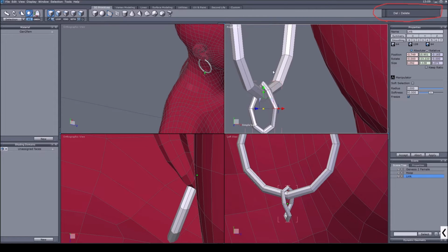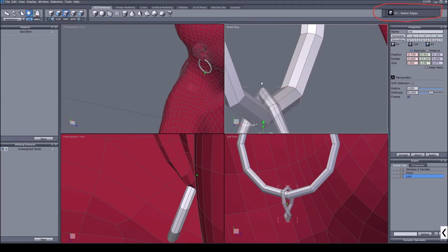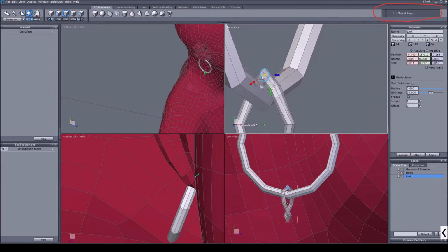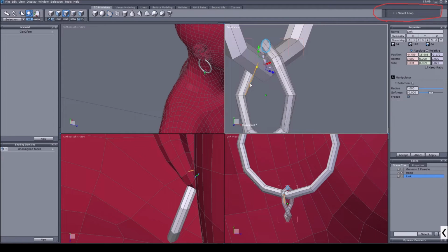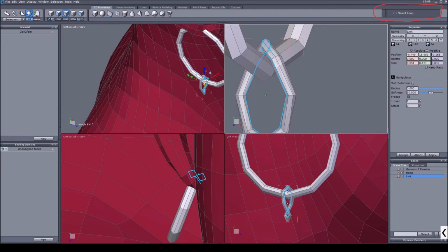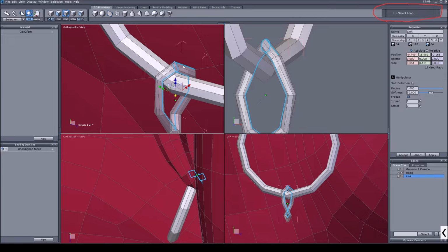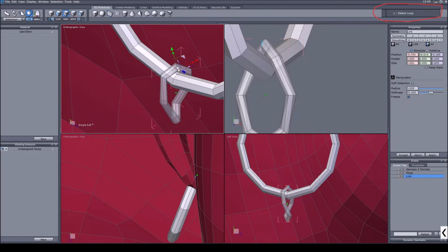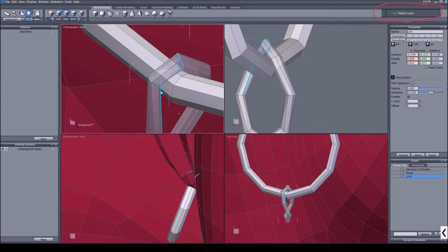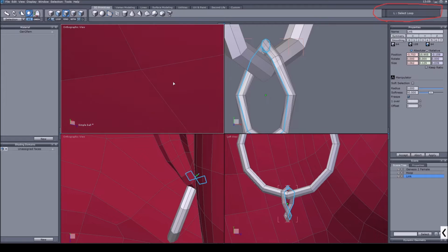Okay, before we go any further, we actually want to set up the UV map right here. For something like this object, I'm usually grabbing two dimensions. One is around the ring, and one is segmenting. So I'm grabbing one of the segmentation rings, and I'm grabbing one of the rings that goes around the length of this.